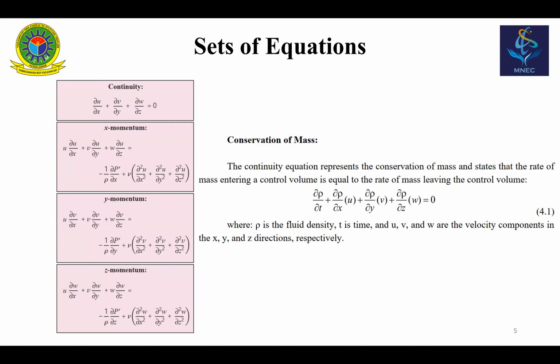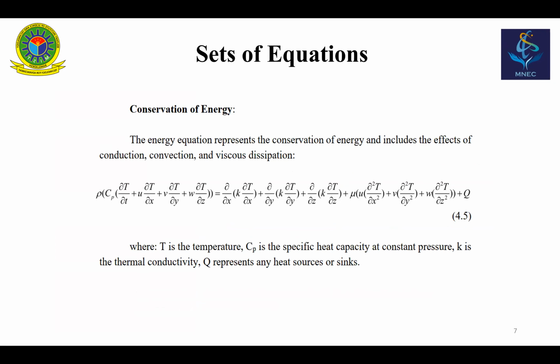Okay. So I'm moving forward. Whenever we try to solve these equations in ANSYS, we have to discretize our computational domain into smaller parts or smaller cells.